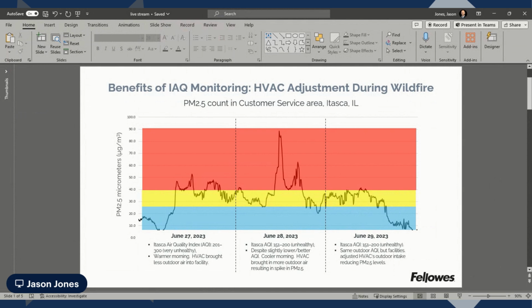The interesting part about all this, at least interesting to me as an HVAC nerd that likes to study this kind of stuff, is that if the event was different, if they were having construction happening indoors, or somebody was cooking a bunch of food, or whatever the issue that would cause the indoor air quality to go bad and spike like this, normally you would communicate with the HVAC system to bring in fresh air. Right. But in this situation, when you bring in fresh air, it's actually bringing in the smoke and the smells and the pollutants from outside. So you're able to communicate with the building management system and tell it, hey, if it's coming from outside, don't bring in fresh air from outside because it's not fresh air, right? Is that a fair statement?